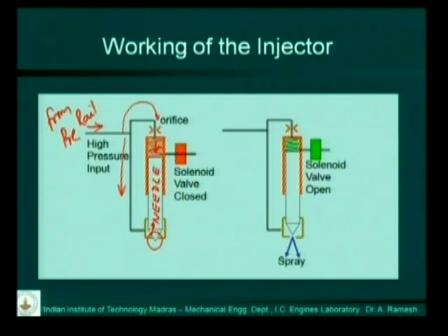It is not used to open the injector. In fact, this is very desirable. If you go to higher and higher pressures, it is very difficult to seal the injector because the injector will start leaking. Now you are using this high pressure itself for sealing. So if the pressure goes up, the sealing force also goes up. So it automatically gets sealed.